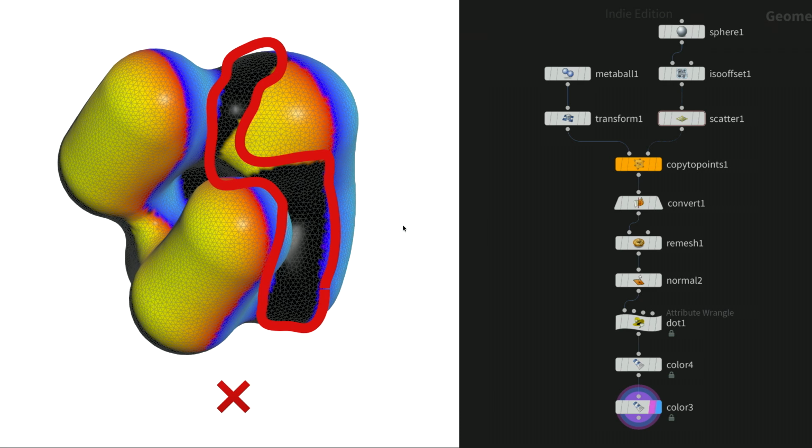For example, currently in the image, the black shaded regions in my test reveal shadowed areas that cannot be seen from the direction of the mold. These areas are impossible to mold without significant modifications. If you're trying to pull it from that direction, and you have any shadows, then you're not going to be able to use it. You're not going to be able to make that part, the hidden part.